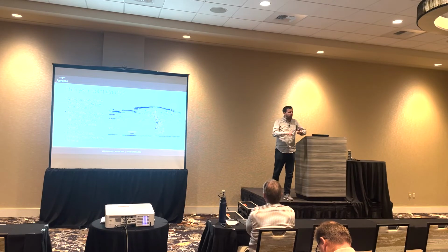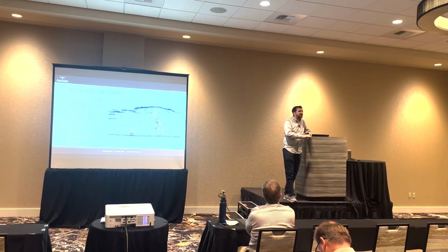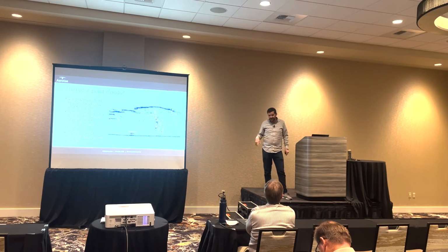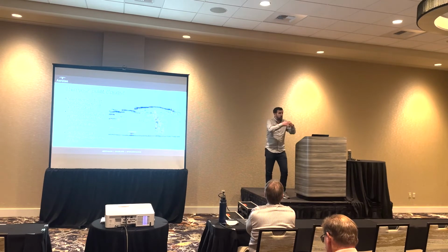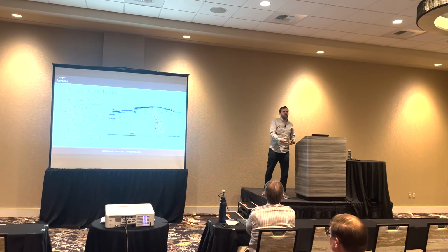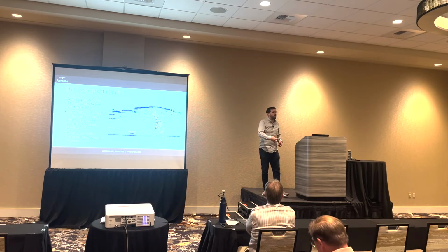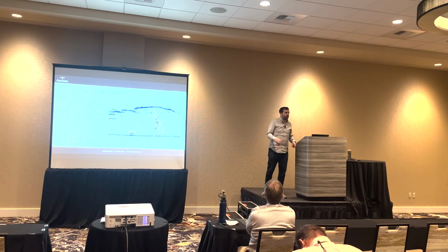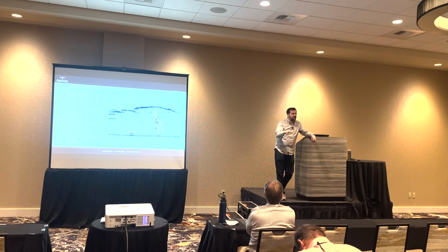Also, your point densities and point precision, actually point accuracy, is going to be very, very different between terrestrial LiDAR, aerial LiDAR, and photogrammetry. Terrestrial LiDAR, because it's so much closer to the subject, and also because it's so much less weight and power constrained, it's typically a much more powerful laser, your actual accuracy is going to be really good. Your curve lines are going to look super sharp. Whereas with drone LiDAR, it's further away, it's typically a lower power laser, your curve lines are going to look a lot fuzzier.